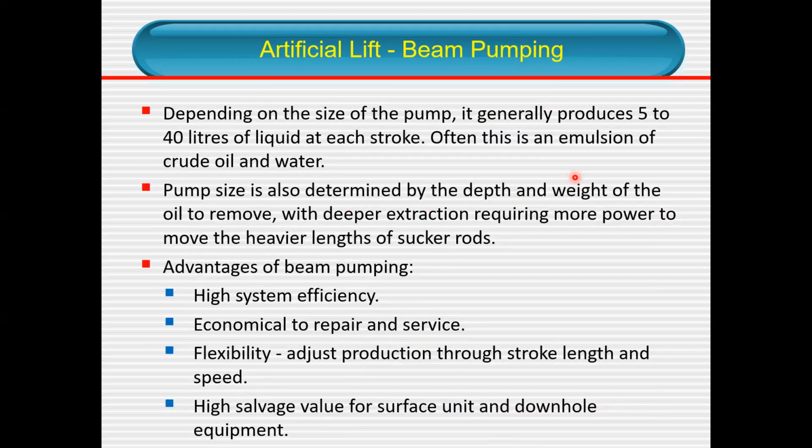Okay, more on this beam pumping. Depending on the size of the pump, it can only produce like 5 to 40 liters of liquid at each stroke. So in a day, depending on the size of the pump, generally speaking, 200, 300, or even for big pumps, it can go 500, 700, 800 barrels per day.